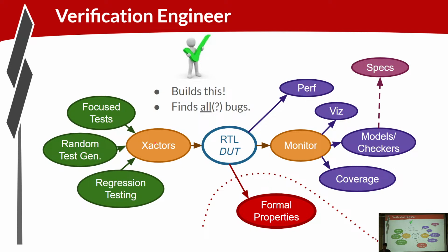So in the case of the CPU, that's pretty simple. That's basically an assembler. You get the code into the model, into the instruction memory. For most designs, there's a little bit more intelligence around taking that stimulus in some higher level description and actually driving the physical pins of the design under test, the DUT, which would be your RTL model. And this happens at all levels, right?